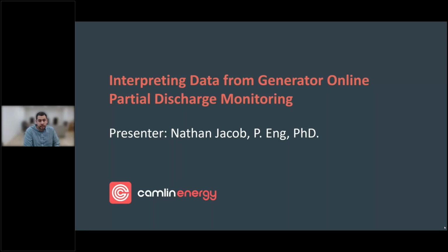Throughout the two webinars, we'll delve into key aspects of generator monitoring, highlighting the current and future risks, the failure mechanisms, and the important topic of data analysis. In today's session, you can expect to learn about stator winding failure mechanisms and the characteristics of partial discharge, analysis of the phase resolved partial discharge patterns and trending analysis, and the importance of correlating online partial discharge data with the operating conditions.